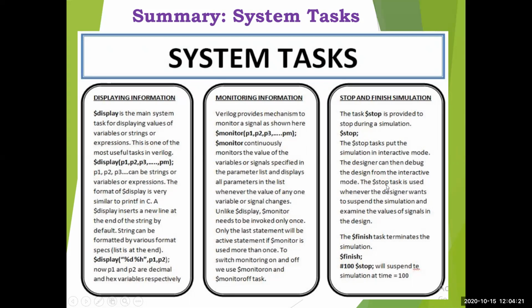So the $stop task is used whenever the designer wants to suspend the simulation and examine the values of signals in the design. And the last one is $finish. This task terminates the simulation. It will stop the simulation, and we have seen an example regarding this. So this is about the system tasks.